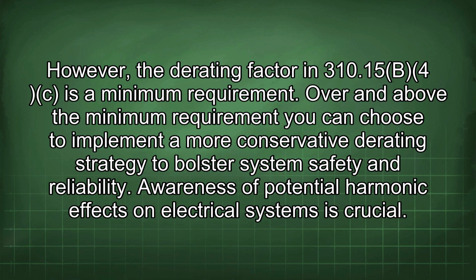However, the derating factor in 310.15(B) is a minimum requirement. Over and above the minimum requirement, you can choose to implement a more conservative derating strategy to bolster system safety and reliability. Awareness of potential harmonic effects on electrical systems is crucial.